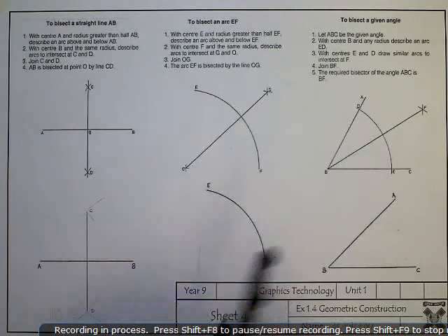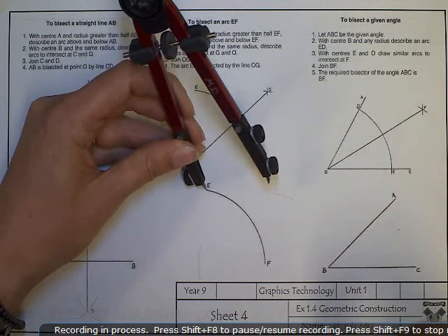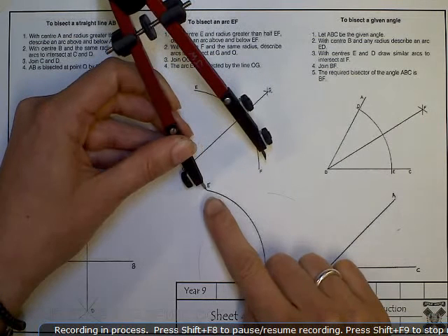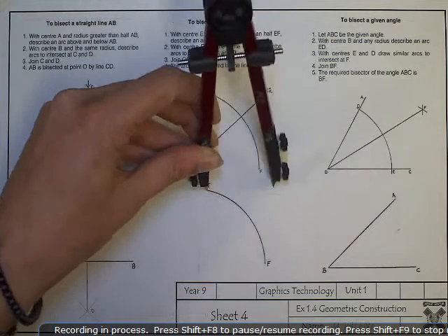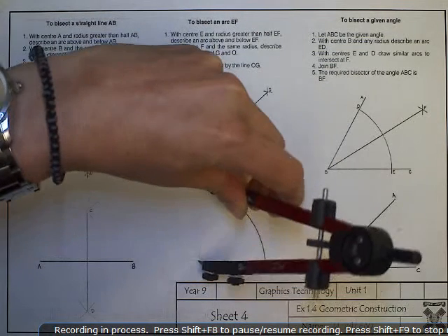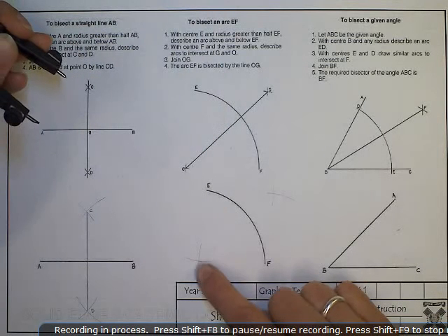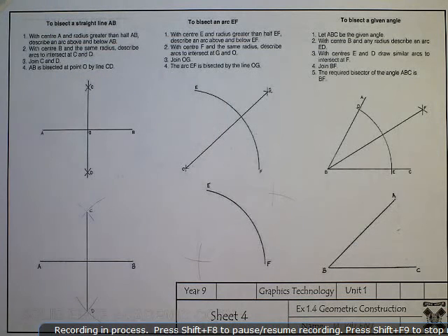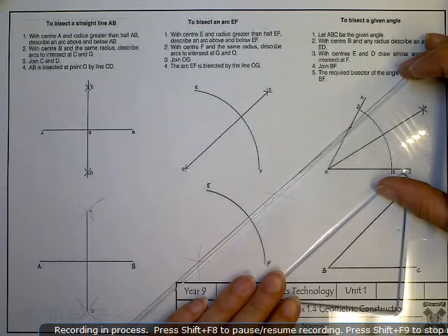Make sure it's reasonably clear to you without being too firm on the page. Now I'm going to set my compass on the other end of the arc, point E, and draw an arc again on either side of the existing line. Okay, now those intersection points, when joined, should bisect the arc EF. We can't use the T-square for this. I'm just going to use this edge of my set square to draw this line.